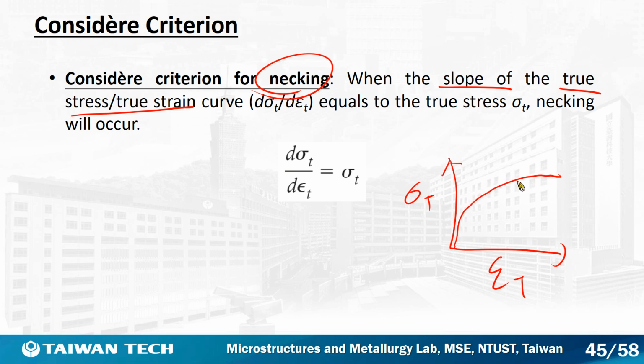And we have a necking point. At the necking point, we have a slope here, and this slope equals the true stress. So this is the Considère criterion.